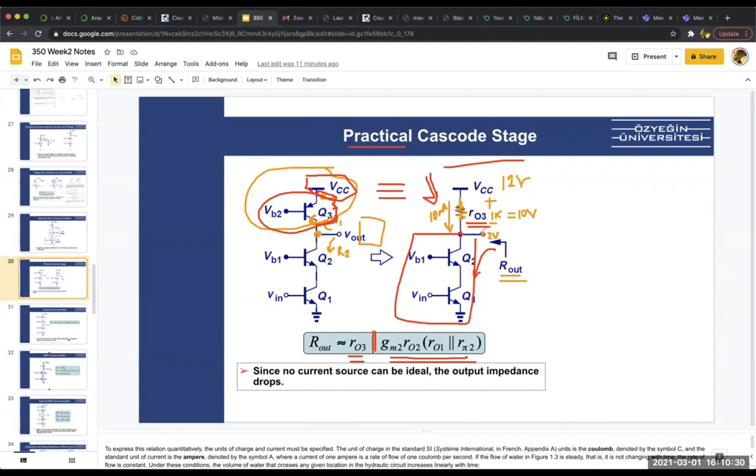Well, 2 volts is extremely small. What does that mean? If we have a swing here, and this is 2 volts, there will be some issues. Assuming this small signal gets amplified around 2 volts DC, let's say this became 3 volts here and 1 volt here. First of all, if this becomes 1 volt, at some point, maybe even less, this transistor will stop working.